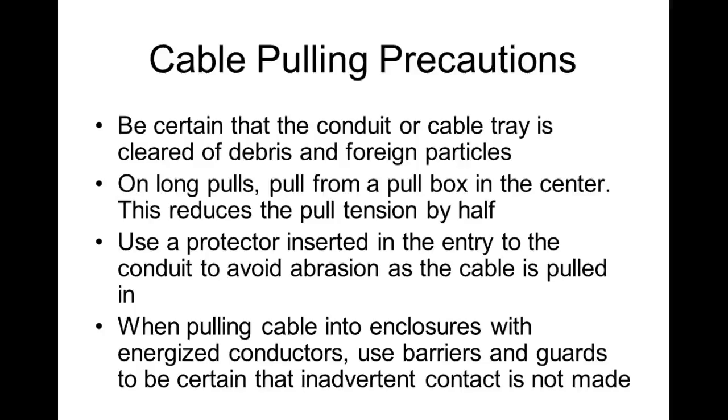On long pulls, pull from a pull box to the center. This reduces the pull tension by half. And we talked about what we call a pull box, right? You understand that? So a lot of times on long runs, and we even see this,